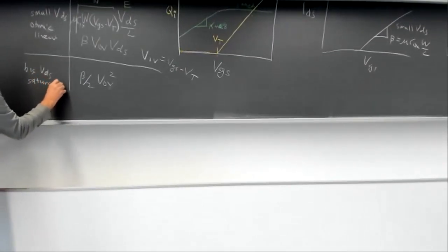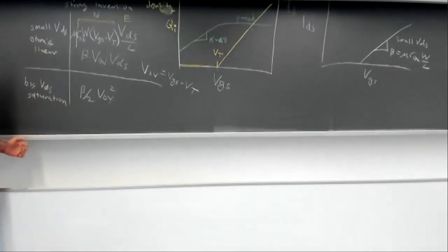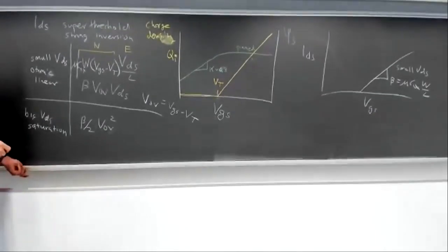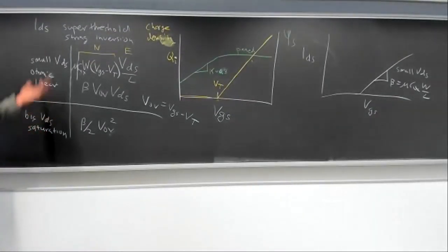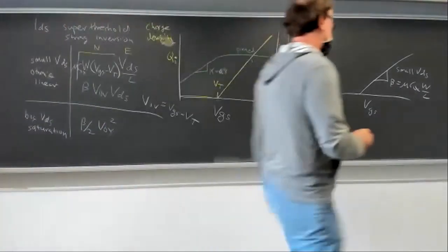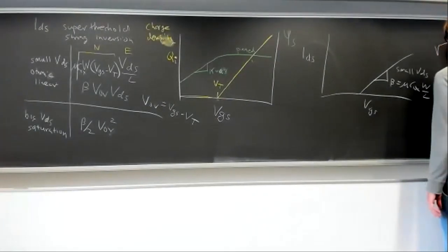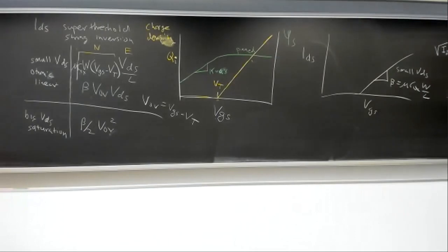Saturation, because when something is saturated, it doesn't increase more. It's full, somehow full. Like the air gets saturated with water vapor. Here, the transistor current doesn't increase when you increase the drain source voltage. In this saturation region, you're going to plot the square root of I, VDS, versus VGS.